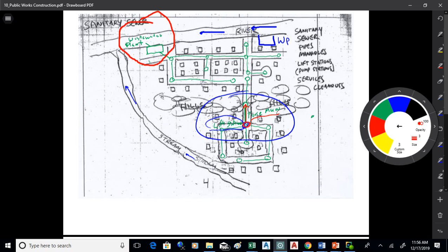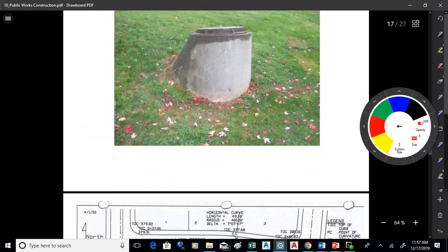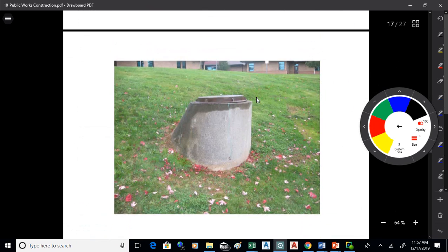Even if you're in flat ground, if you run a sewer main for a long distance, it's going to have to slope down, so it's going to end up getting deeper and deeper and deeper. And somewhere around 15 or 20 feet of bury, it's just too tough to maintain something like that, so you'll put a lift station in there to lift the wastewater back up to a more reasonable depth of bury on the pipes. Okay, so again, there's a manhole, and then there's pipes that run between the manholes.